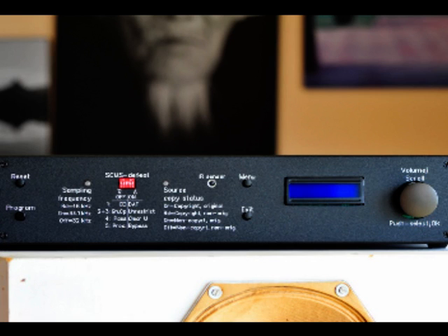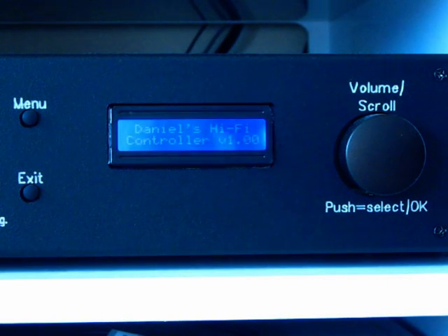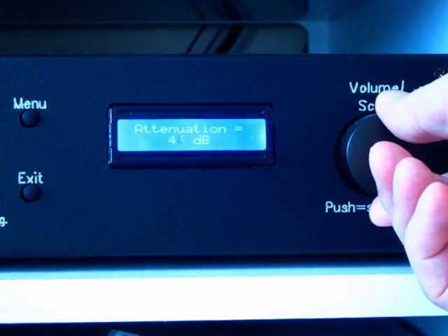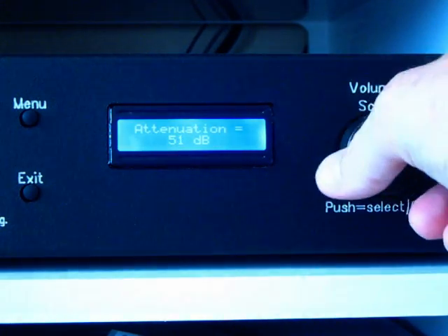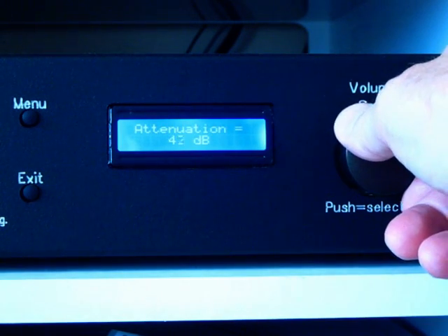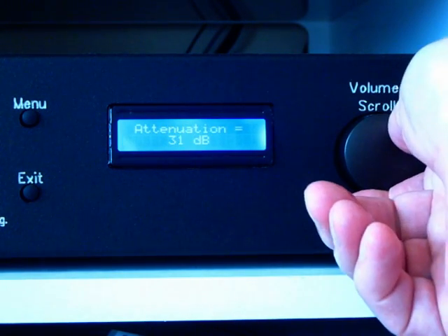For the rare occasions when the touch PC dies, it has happened once in the 10 years I've been running it 24/7, I programmed the Switchbox so that most of its functions can be controlled manually from its front panel. Here's a brief demo of just some of that capability. When not in a menu, the main control knob, which works via a quadrature encoder, changes the playback volume, more strictly attenuation, which is how I prefer to display it.